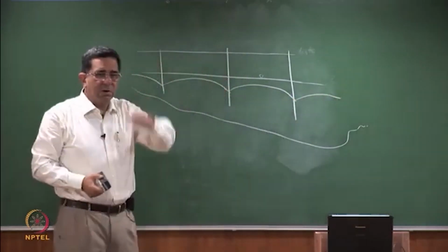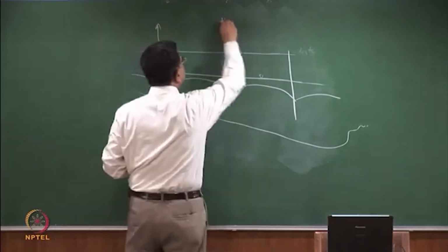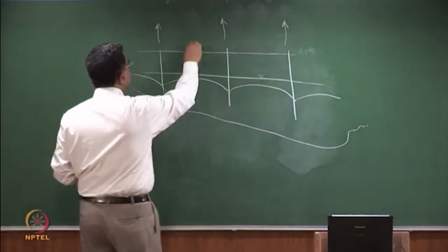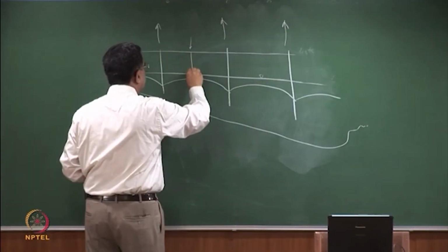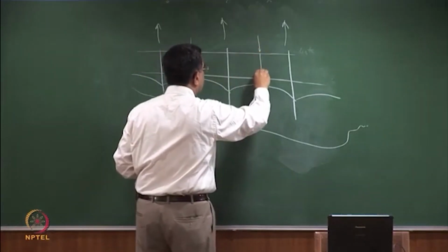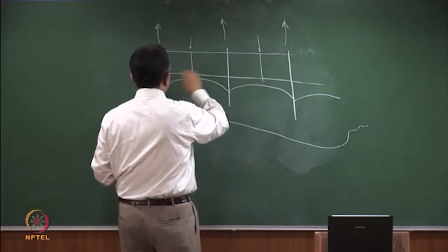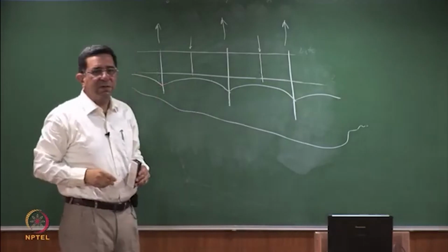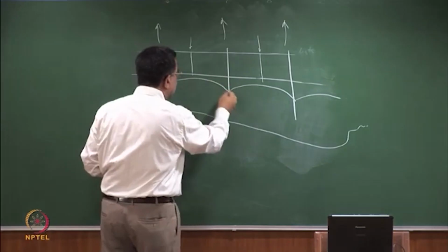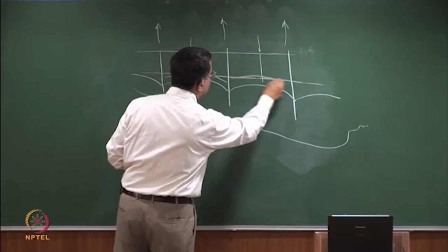Agree? My groundwater will lower, and I'll be extracting and sending it to treat. So I'm pumping out the groundwater. If I now put in some injection wells, then what will these injection wells do? These injection wells will raise the level of this depleted zone, and they will try and bring the level back to its original position.